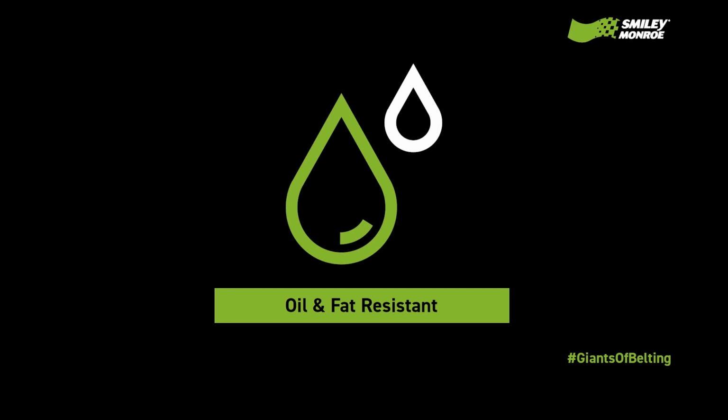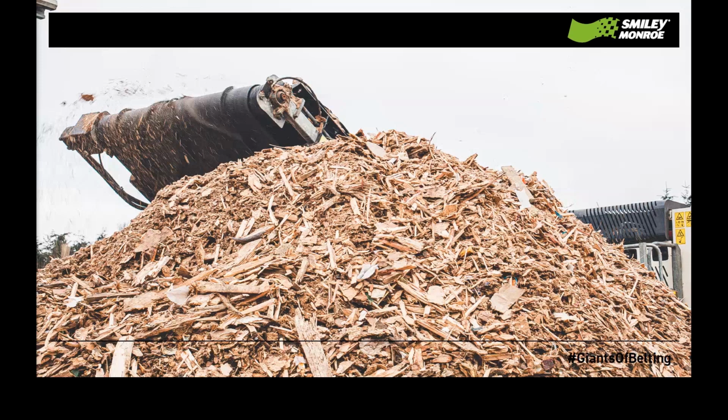And finally, oil resistant belting is designed to resist swelling and delamination in oily environments. Standard belts will absorb the oil and curl up at the edge and become difficult to track. It is often used to convey waste, grain, fertilizer and wood chip. So finally, Ryan will briefly discuss Zipclip belts, which we covered in greater detail in our last webinar.